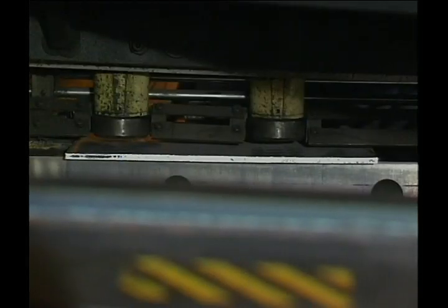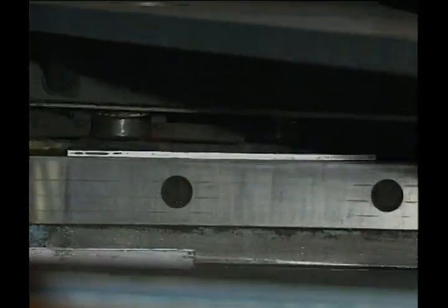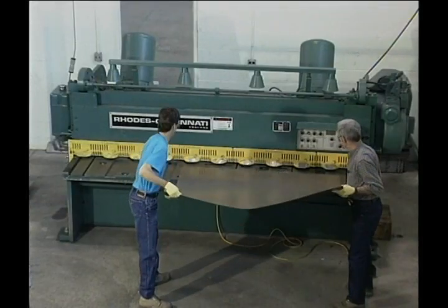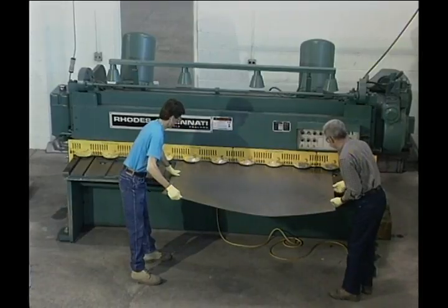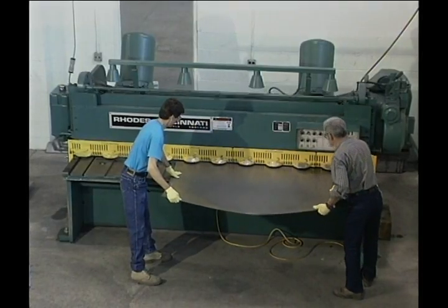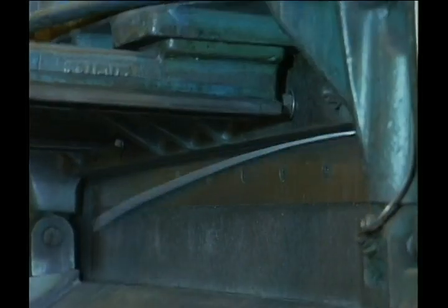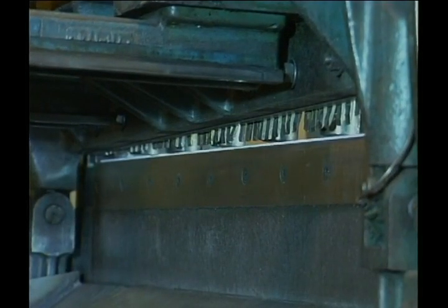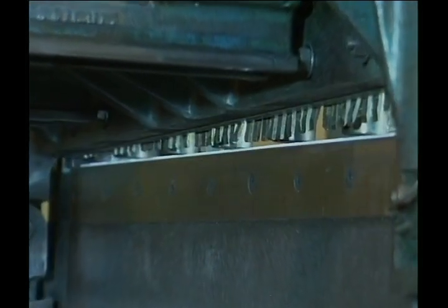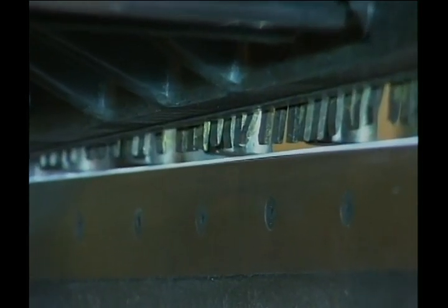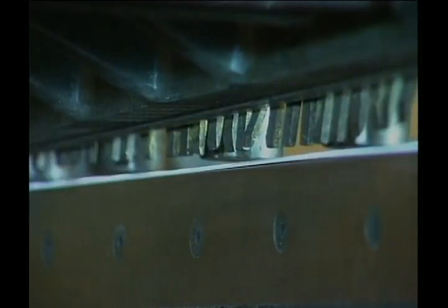Let's review the material contained in this videotape. Shearing is the mechanical cutting of sheet metal by means of two opposing blades. It is used to precisely cut large sheets of plate and sheet stock into smaller, more manageable sections, which are then used in later operations. Typical shears consist of a fixed lower blade mounted on the table or bed of the machine, and an upper blade secured onto a vertically movable crosshead.